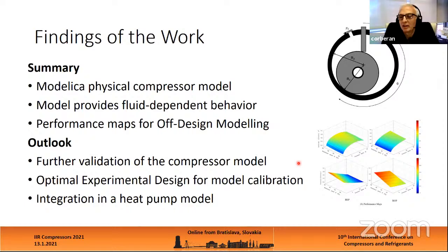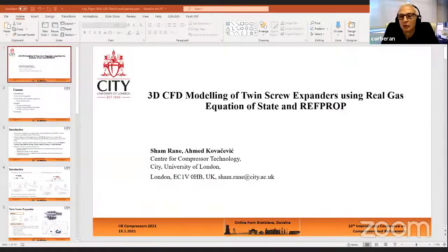What I mean is that if you need to validate an unsteady model like yours, recording with a pressure transducer inside the volume is essential in order to register the instantaneous pressure diagram and then validate the calculation. That was my question.